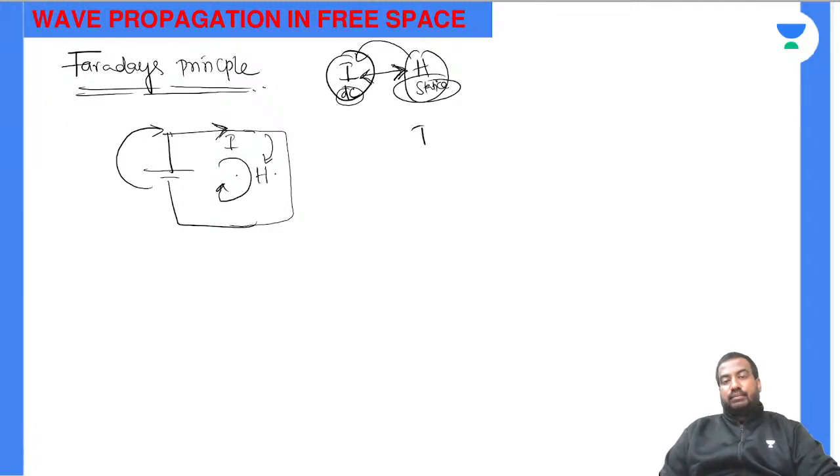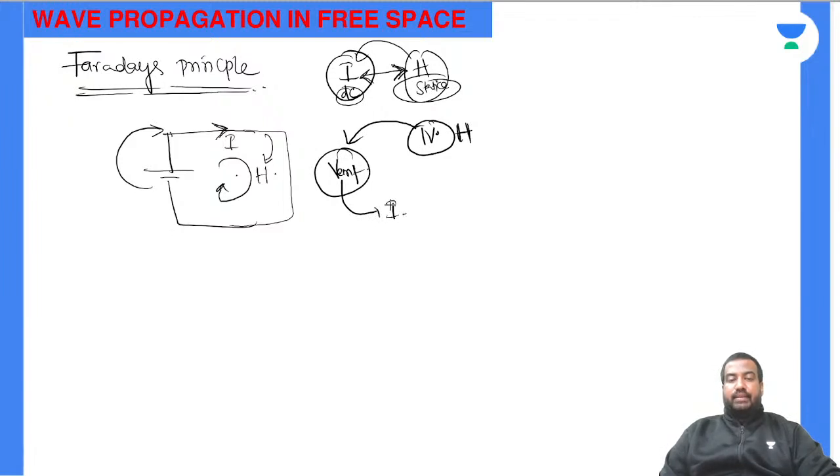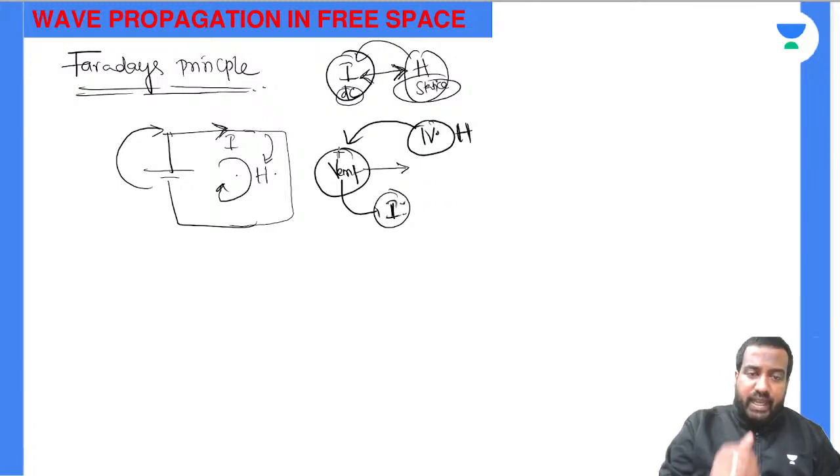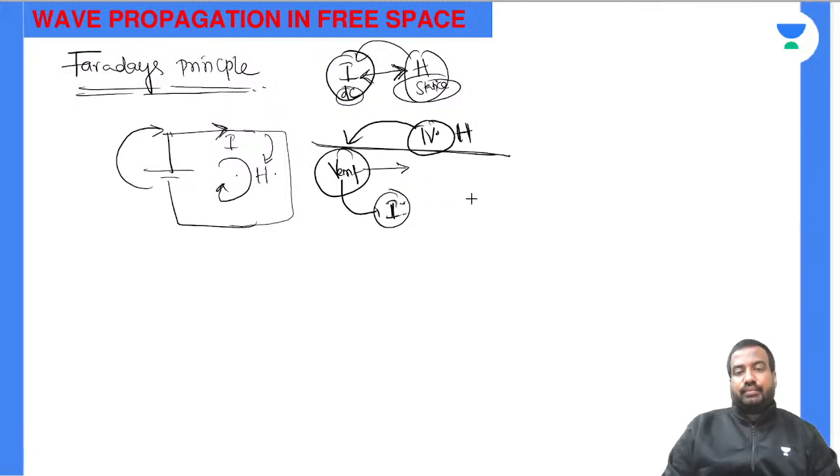Rather, a time varying magnetic field will induce a voltage named EMF, which is indeed responsible for the flow of current. Such induced EMF will be equal to the rate of change of flux linkage. From here, we write Faraday's law.